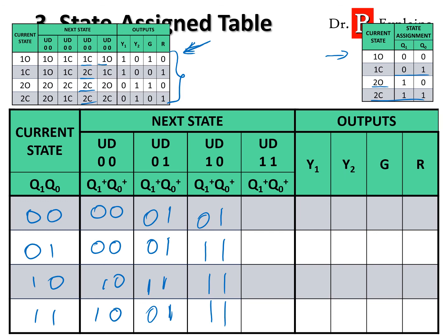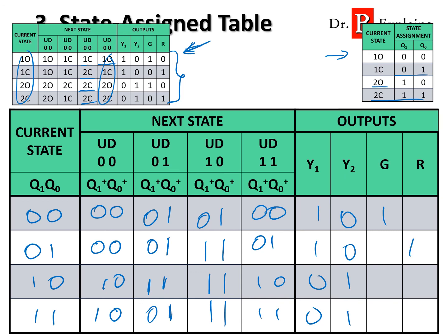Last one, this one, it follows the same order of this, right? And we said 0 0, 0 1, 1 0, 1 1. In the case of the output, remember we had first floor, second floor, second floor. And then we had open, and then this one was close, open, and close. Okay, so that's it. We just have to rewrite the state table using the assignments now.